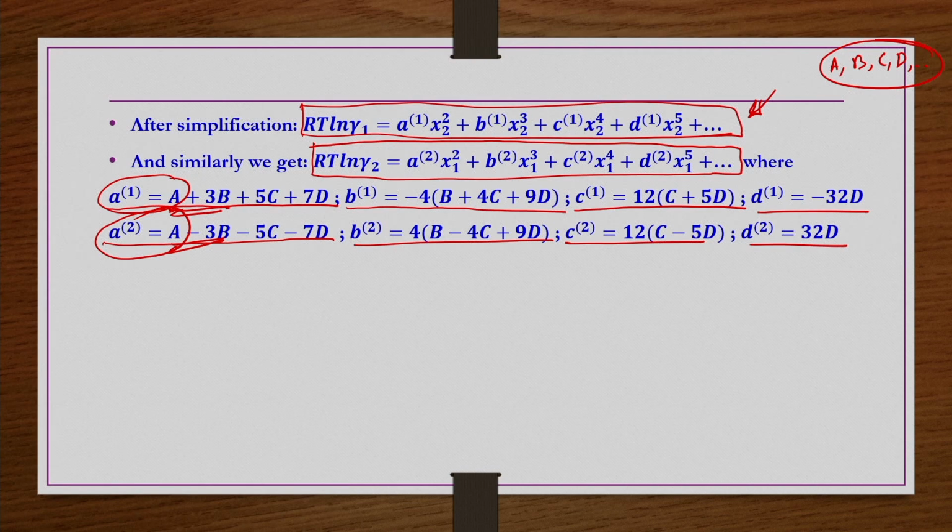That depends on the system primarily, but that again depends on the available experimental literature. It has been found that having 2 constants is more than sufficient for the majority of systems. Very rarely do you need the third and fourth parameters in the GE expression. Even if you do, in order to include those third and fourth constants, like capital C and capital D, you need a large amount of data, and very reliable data, to make a reliable curve fit for those C and D parameters.